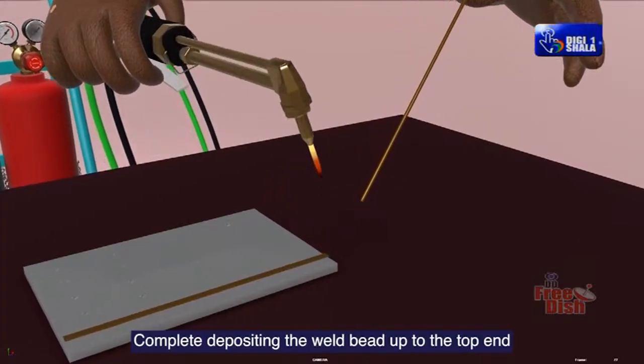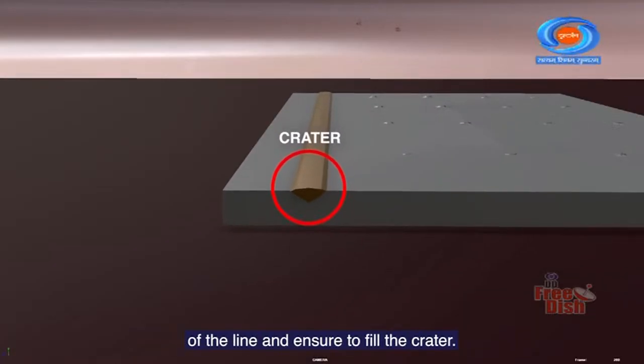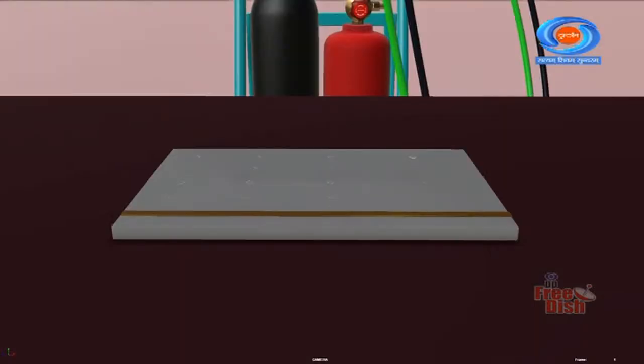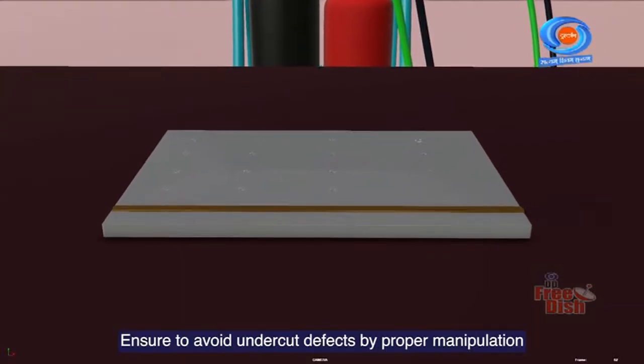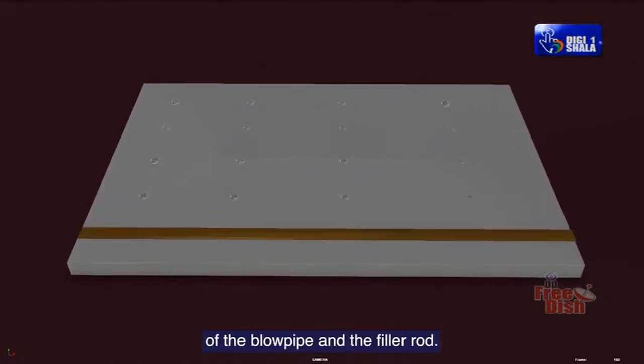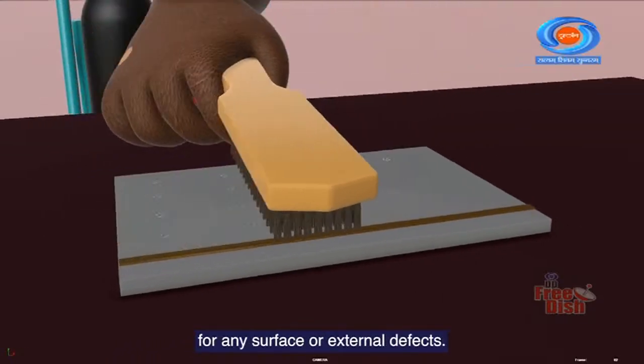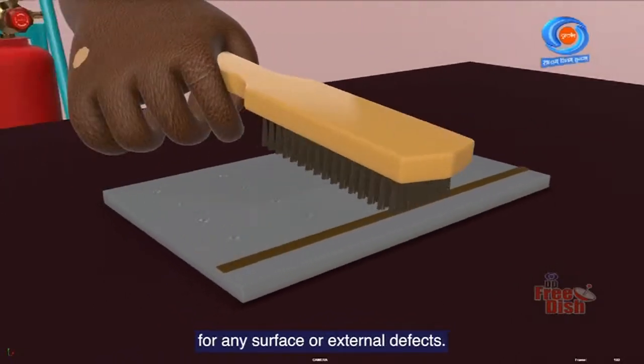Complete depositing the weld bead up to the top end of the line and ensure to fill the crater. Ensure to avoid undercut defects by proper manipulation of the blowpipe and the filler rod. Clean the bead and visually inspect for any surface or external defects.